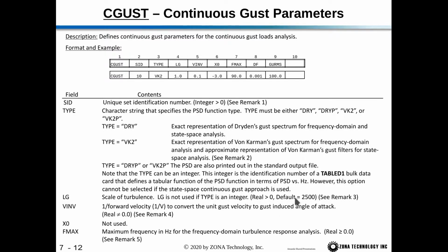So note the default is not 2500 feet. The default is just a value of 2500. So you want to make sure you're using the correct units. So I would recommend always just typing in the value for LG.